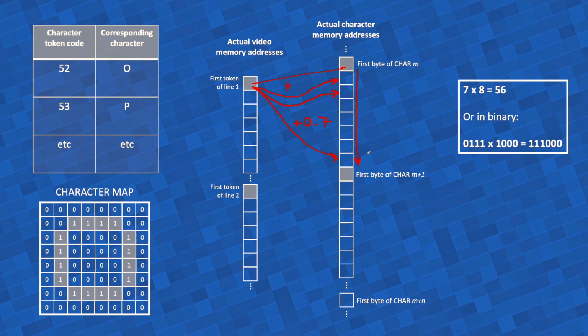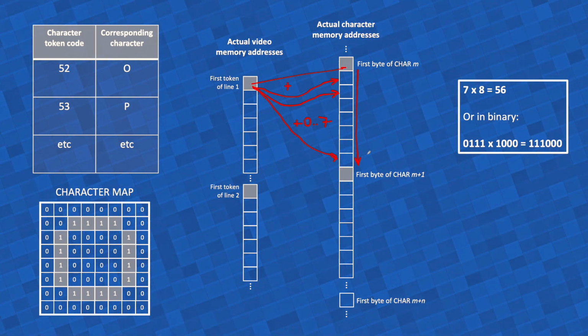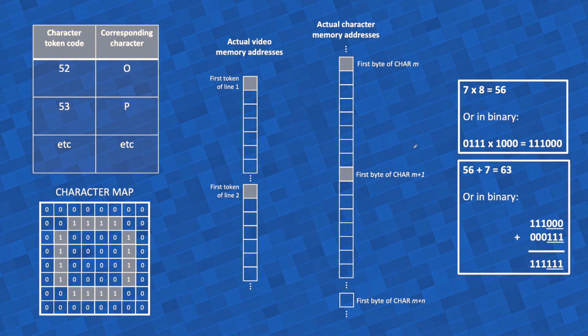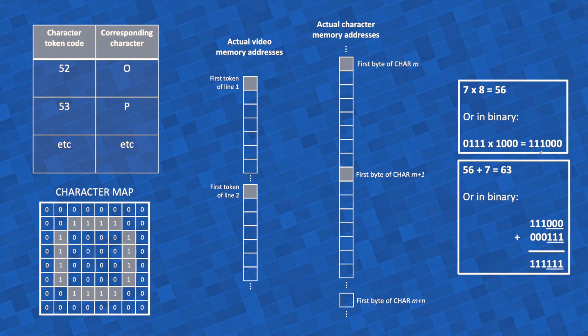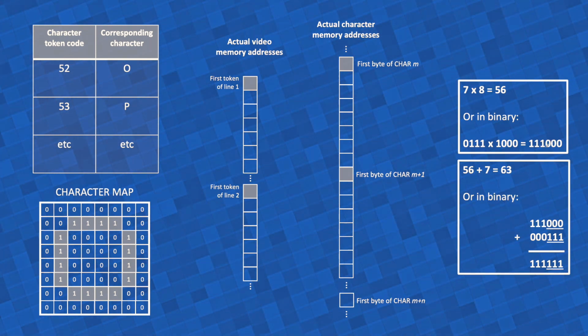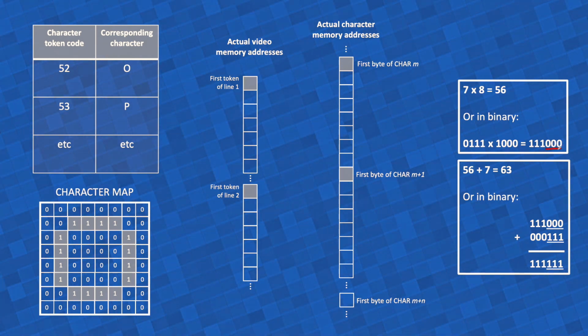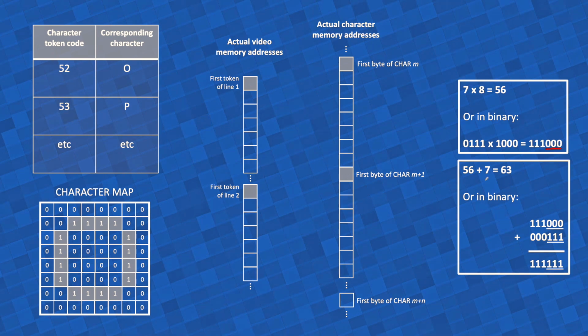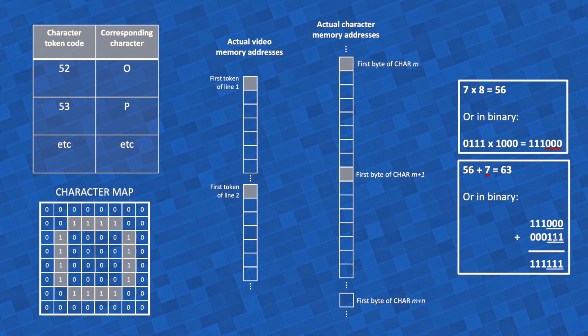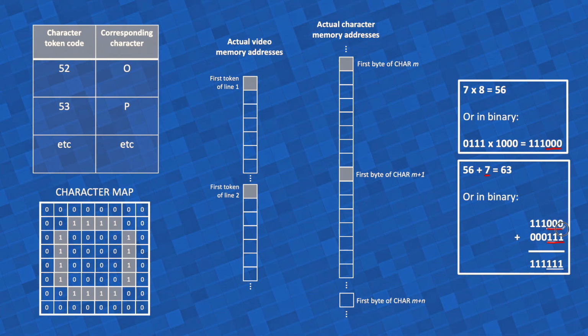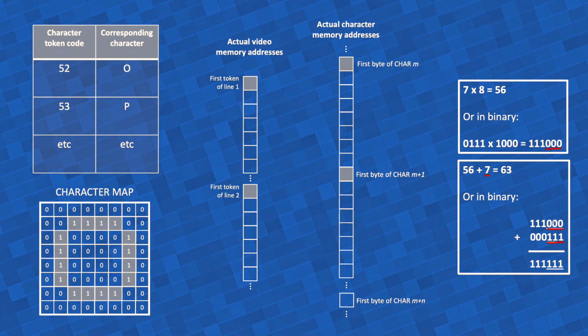So do you need a ripple carry adder circuit to do this? No, you don't need that either, because if you shift everything to the left by 3 positions, then you know that the 3 least significant bits of the result are always 0. And 7 in binary is 1, 1, 1. These will overlap exactly with the 3 zeros of the operand.